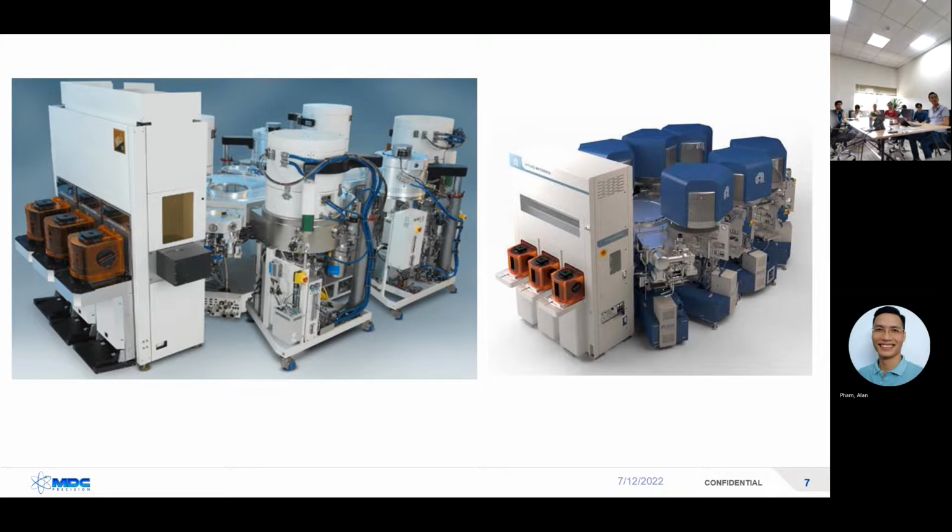So part of the process that's going down outside the chamber are things we don't necessarily want, but they're still there, which are carbon fluorines that are still together. As they go down and find a piece of this gas pipe, they stick to it. Over time, we build up basically a Teflon layer, and it gets thicker and thicker and starts to flake off and causes particles. That's kind of not important, but you start to understand why we sometimes try and get high layers.